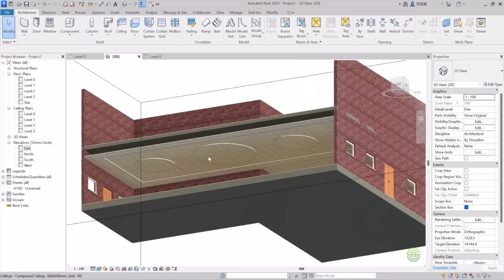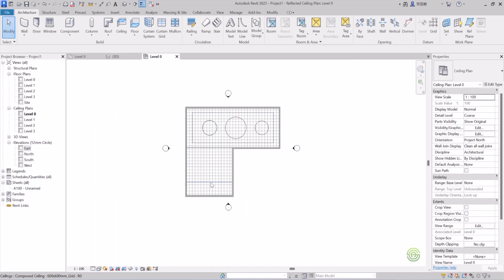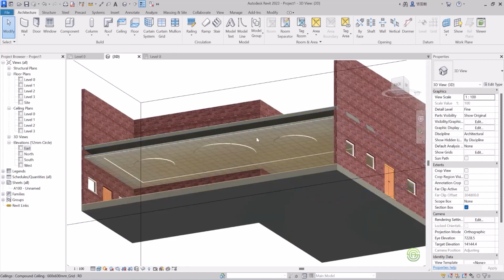Using automatic ceiling, it is easy. To create a ceiling using automatic ceiling, we just have to move the mouse on the plan. Automatically it will analyze the surface and create the ceiling. For sketch ceiling, we have to draw profiles like this randomly using line tool or spline tool or even rectangle or circle tool like this. We can create this false ceiling in this way.